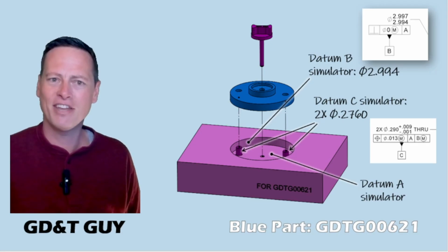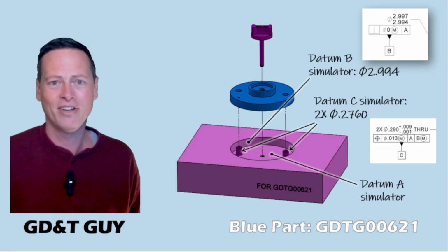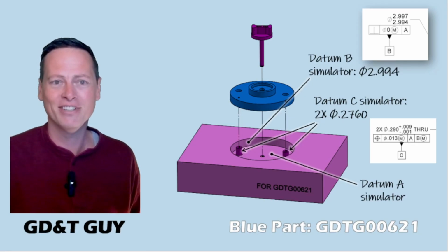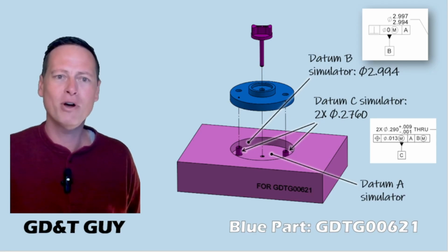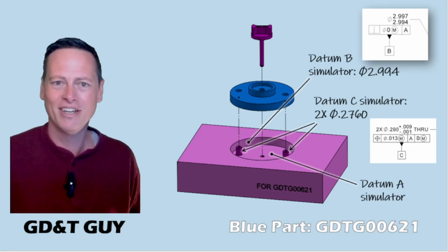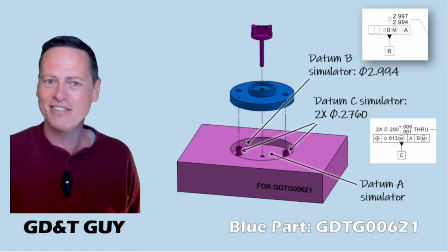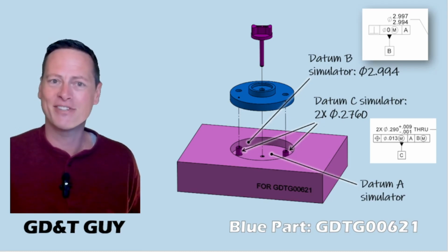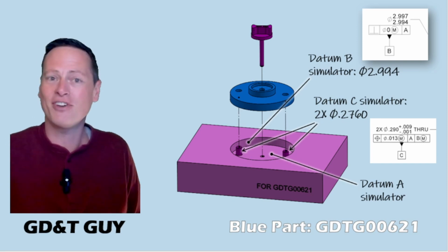This is a little edgy, I think. I mean, now our tertiary datum simulator, supposedly one DOF, only constraining in rotation, is also now at 2 cylindrical features, our most complex datum simulator, compared to 1 cylinder and 1 planar feature. Does that make sense? And if these look complex and constraining, just remember, these holes could also be slots.